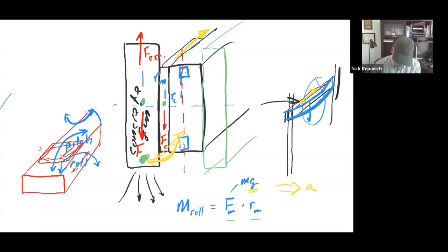And so this bearing here would begin to see a yaw moment. What do you do with that? You do a quick calculation. How big is it? It's the same thing: what's the force due to acceleration, and what's the distance it's acting on? So in this case, this R would now be your new distance to look at the yaw moment.